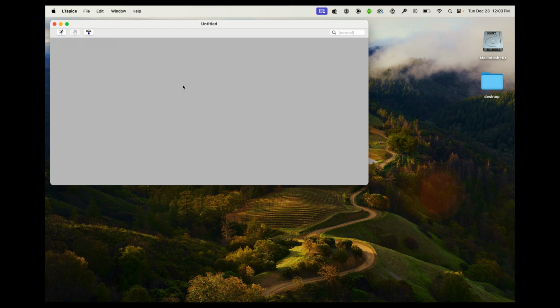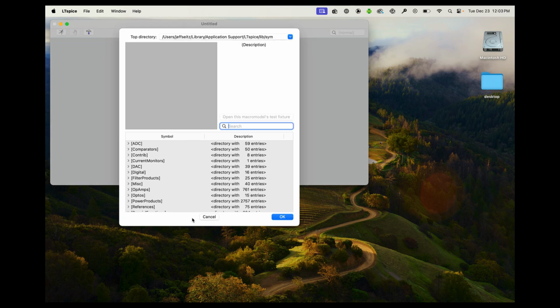But certainly if you're trying to find components or how to rotate things, none of these buttons are now at the top of the screen. Everything we do is going to be a right click. So I'm going to right click and we get this little menu. I can go to Draft and I can say, let's add a component. You notice F2 is the shortcut for that. So this will bring up our component directory, and I want to add a voltage source.